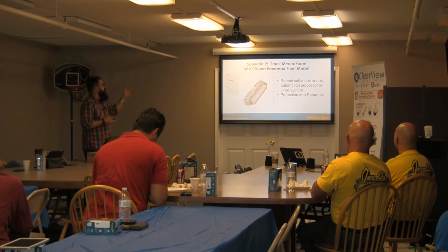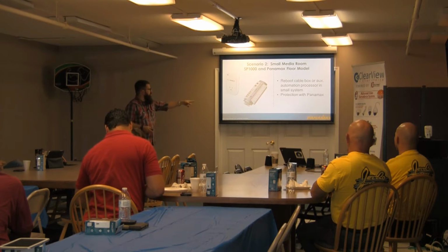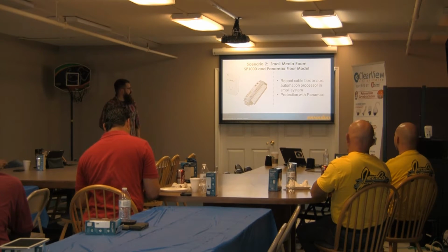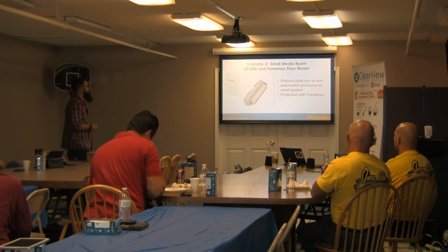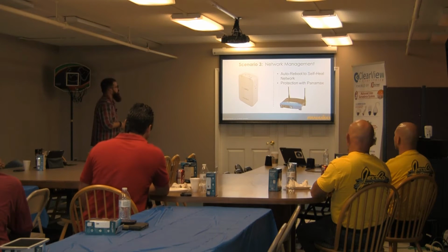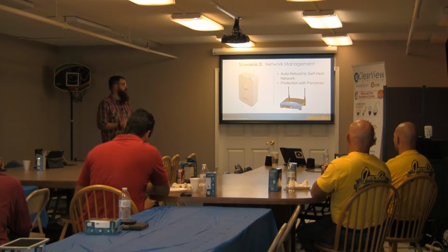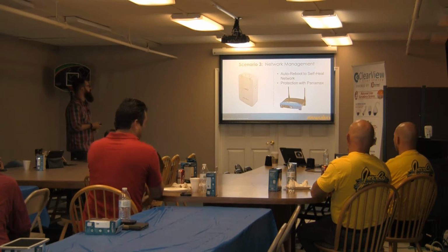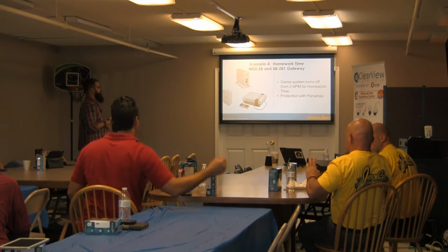The small media room. If you're just doing a local system with a couple sources, you can put in an inexpensive Panamax floor strip and put in an SP1000 on there so you get the remote reboot. Network management. We talked about this, how we do auto reboot to self-heal the network once a week. Reboot your router, reboot your modem, open up that bandwidth again. Self-healing feature there.